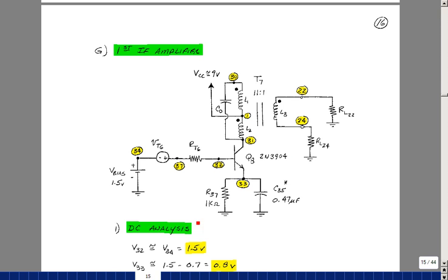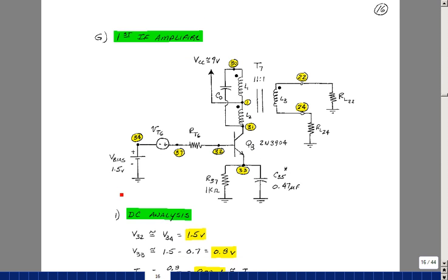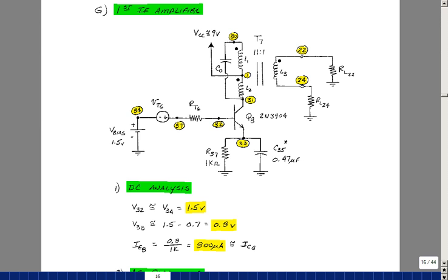Here too I yanked this out, and this stage is feeding the second IF amplifier, which has a differential input. And so I'll show it as a resistance back to ground and back to ground. What's biasing this amplifier is the output of the automatic gain control circuit. So let me just put a fixed battery here, and then I'll vary this and we can see how the performance of the circuit varies. Here too, again, I've got to maybe approximate the DC and AC results so that I can get a rough handle on what the gain might be. And we can run SPICE again and see how close we are using the same models. And then of course we could put in more detail and see how close we come to the actual measurements.